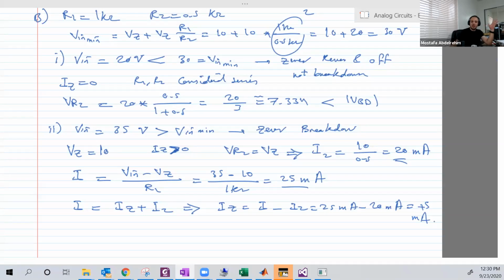If you assumed it with a regular polarity, I from B to N, it should be minus 5, which is the same, which is also correct, because we are working in the breakdown. So with the regular polarities, the voltage and current are negatives. But with this new polarity, IZ and VZ, they are both positive.